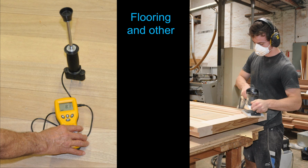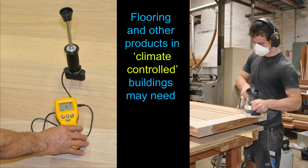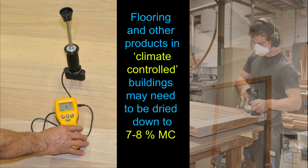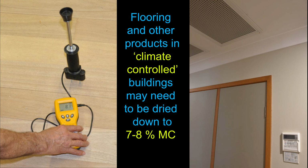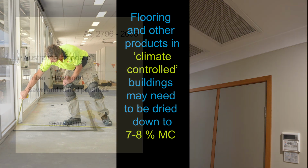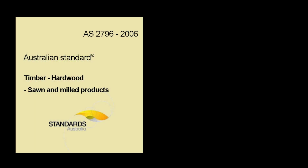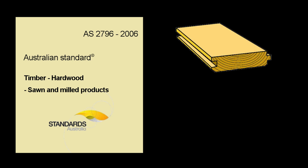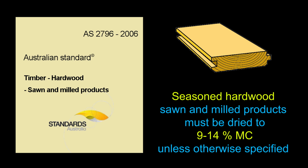Flooring products and high-grade joinery items installed in climate-controlled buildings may need to be dried down to a lower level, typically 7 to 8%. This is because air conditioning systems have the effect of dehumidifying the air, especially in buildings with sealed windows. The Australian standard that covers milled hardwood products, such as strip flooring, states that seasoned hardwood must have an MC range of 9 to 14%, unless otherwise specified.